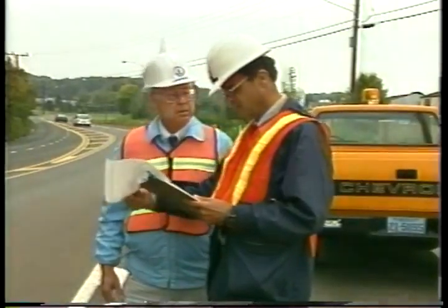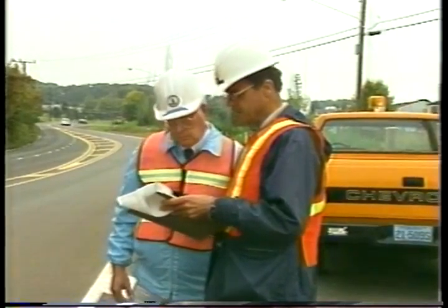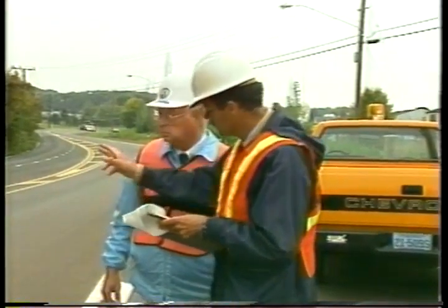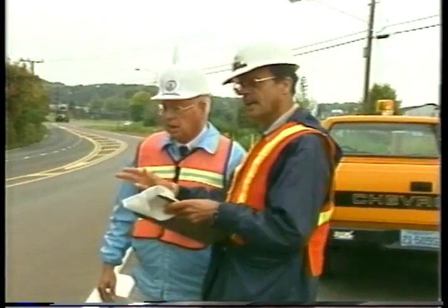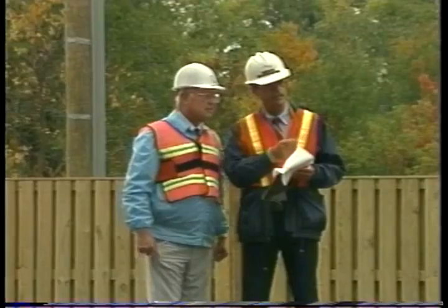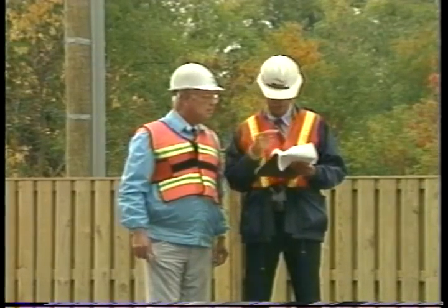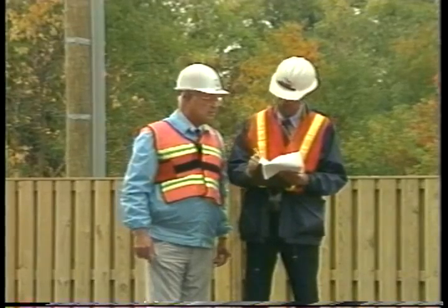Traffic control planning is not over even when the work is complete and the work zone is removed. It is an ongoing process. A safety review is performed annually. It includes all roadway activities, with an emphasis on nighttime operations and device retroreflectivity.